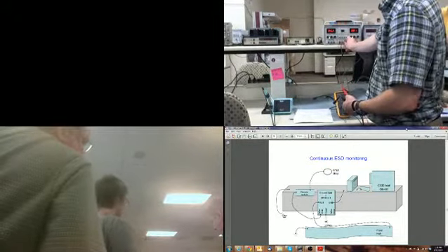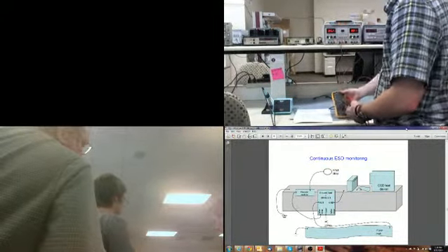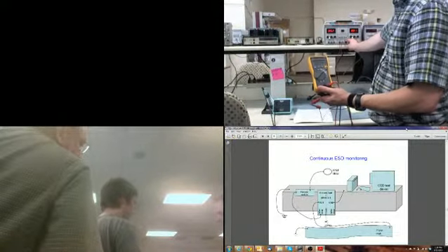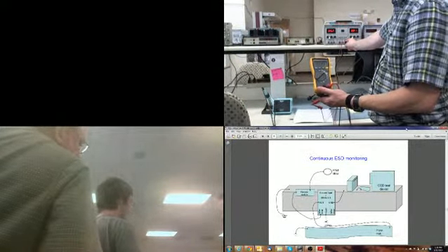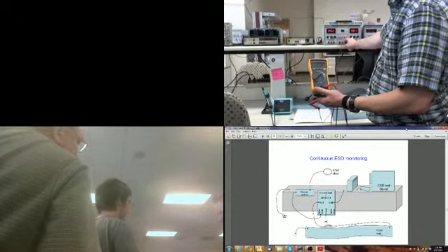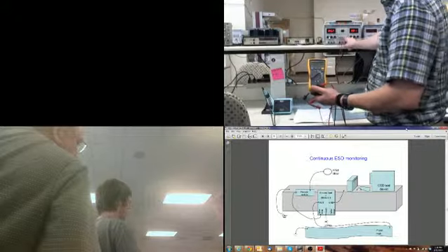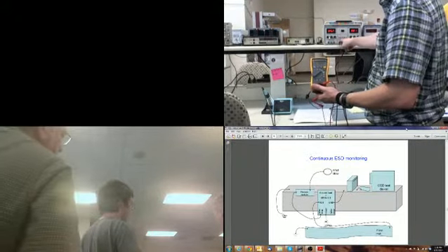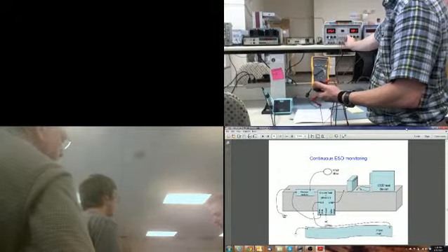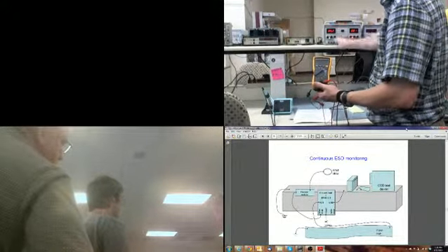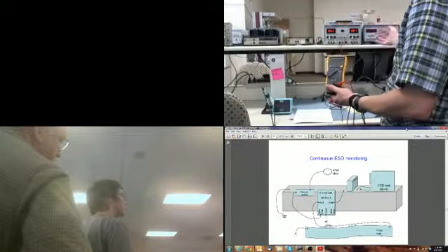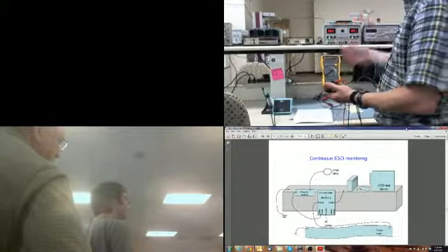5.5. Notice that you can change that. This says 3.9. I can turn this knob all the way up to about 5-6 volts. And so this one you can use for a basic digital. Sometimes people use this for digital. If you have some digital circuitry here, maybe over here you have plus or minus 15. So you can have plus or minus analog voltage, and you have a 5-volt digital. So that's really what that's for.